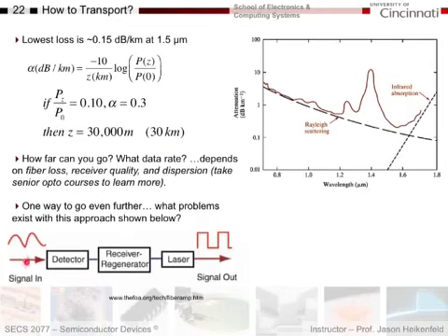You could basically say, here's my signal coming in, I have a PN junction photodetector, I have a circuit that would regenerate the digital pulse because it comes in a little bit noisy by the time it gets there. And then I would have a laser here which I would modulate again with that split waveguide, and I get my new data out that's nice and amplified and clean. But what's the problem with this?